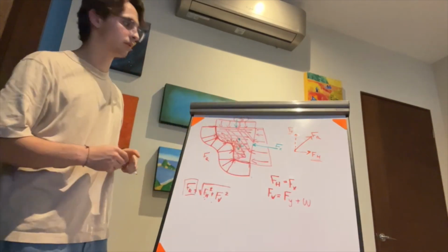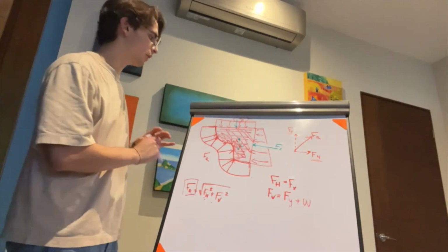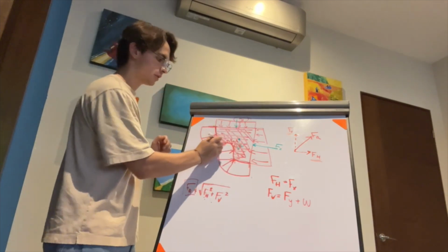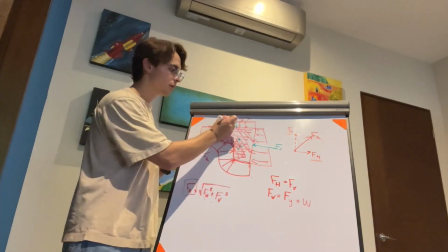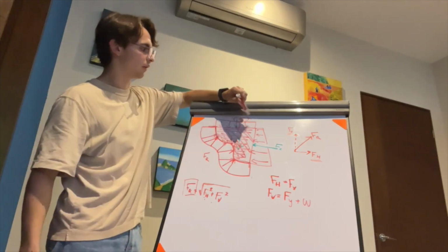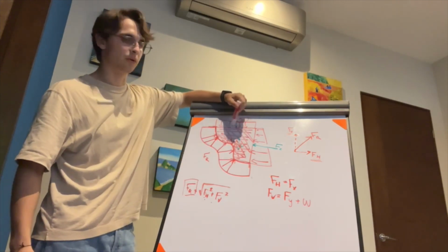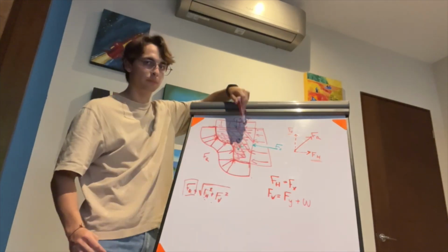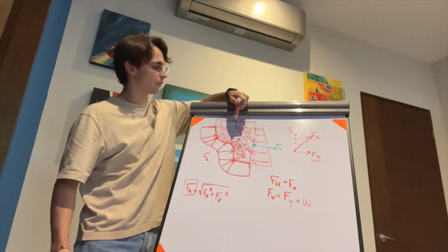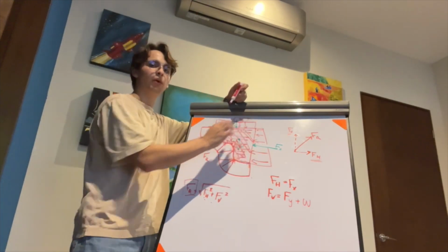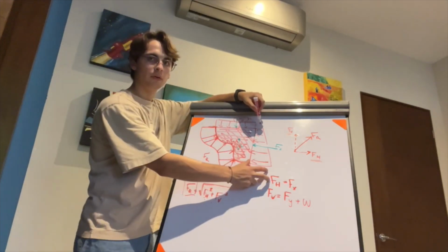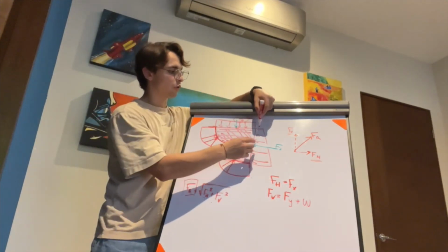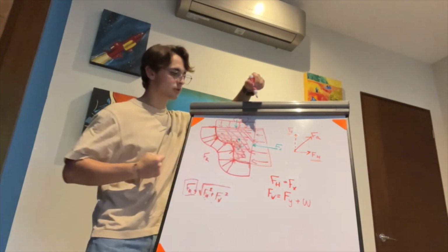You can see this graphically: here we have a tank with a curved surface, and here you would take this as the resultant force. You have the hydrostatic forces on the horizontal cut, in the direction of Fx, which would be distributed evenly. And on the vertical part of the cut, we have the distribution of forces that, as they go down, increase.